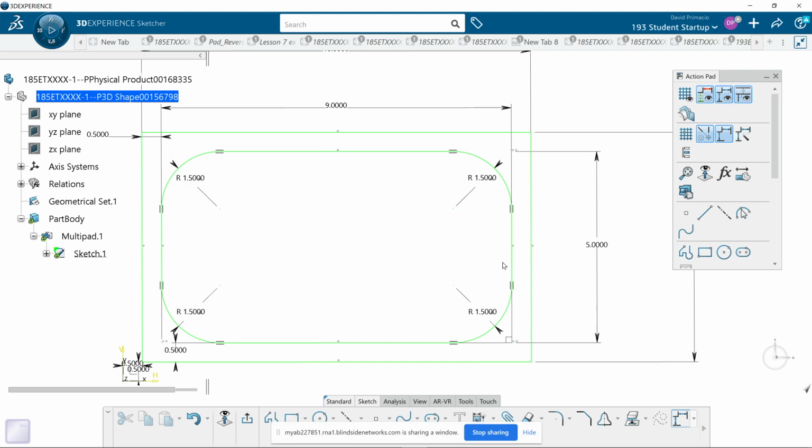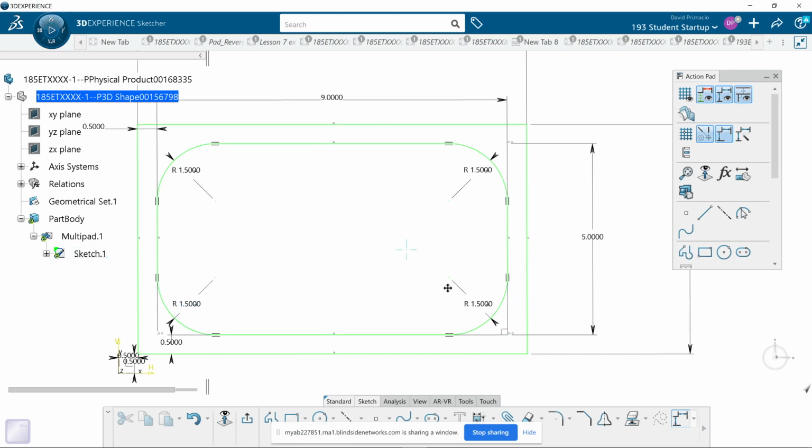Now, if I started machining here and I went this way, and then came over this way, and then came up this way, what direction am I going? Negative. I'm going in the negative direction. Clockwise. I'm going clockwise, and then all negative radius values. Okay?